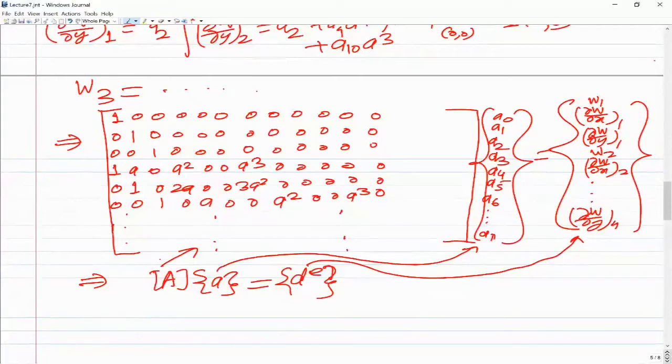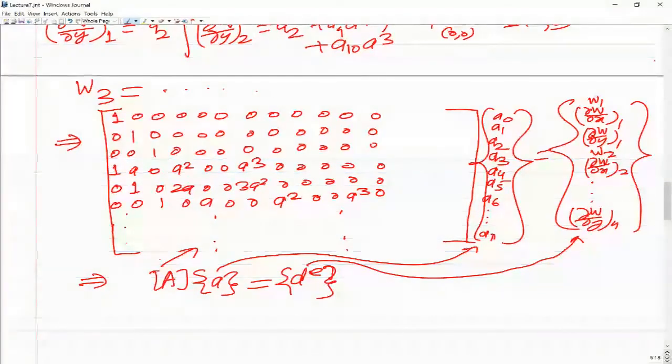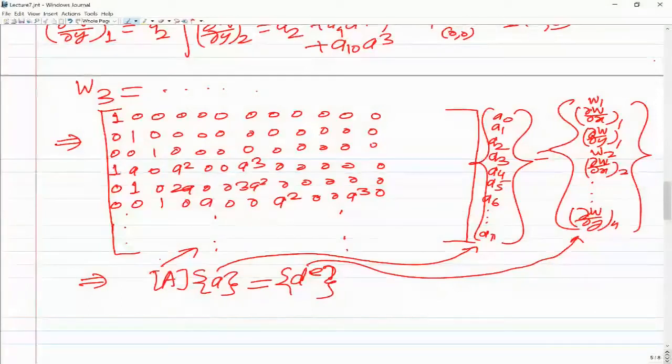Yeah, it is not compatible, but this element is simple. So still sometimes we use this element. It is not that it is not at all used. Of course, when you are using this element, you have to ascertain the convergence properly. But this element is also used. That is why we are discussing it and want to formulate it. The advantage is that at nodes we have degrees of freedom which are physically interpretable as geometric quantities, deflection and rotations. So this element is actually still used. That is why I am discussing the further development of this element.